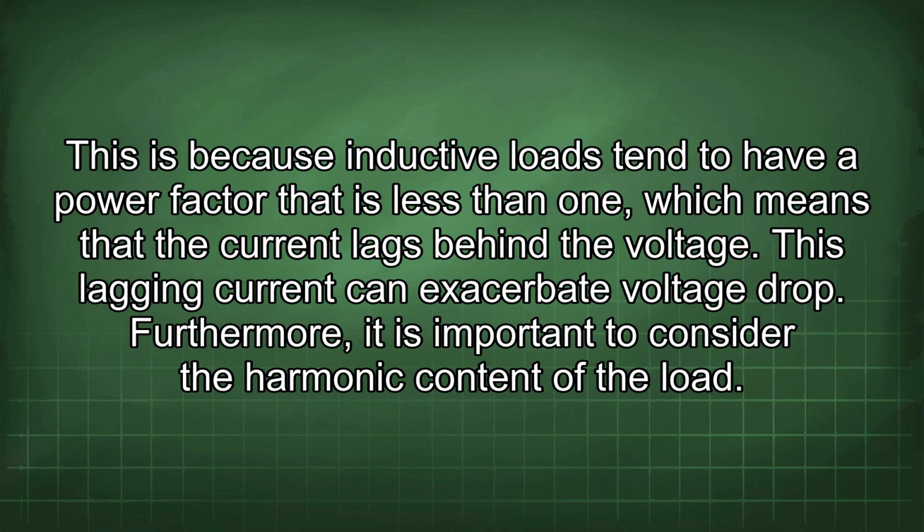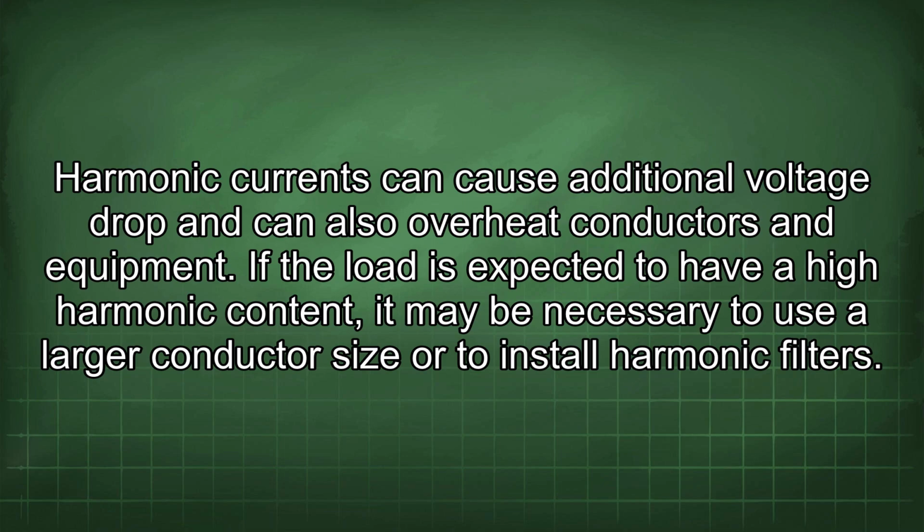Furthermore, it is important to consider the harmonic content of the load. Harmonic currents can cause additional voltage drop and can also overheat conductors and equipment. If the load is expected to have a high harmonic content, it may be necessary to use a larger conductor size or to install harmonic filters.